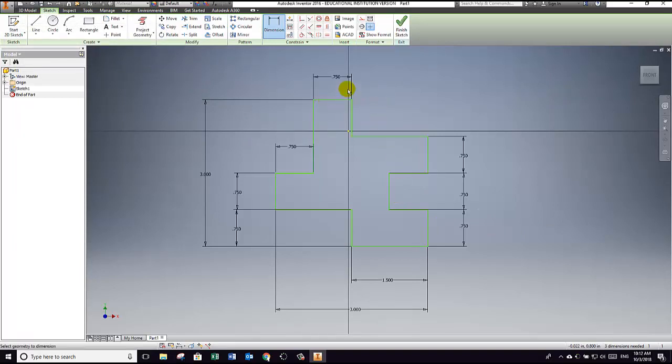Now I'm going to show you something. If this piece is fully dimensioned, if we have all the measurements we need, then when I click on the little padlock and click on a corner, it should turn purple. Now the reason that shape right there did not turn purple is because if I click on it, you'll see I can still move it. If it was purple, I wouldn't be able to move it.